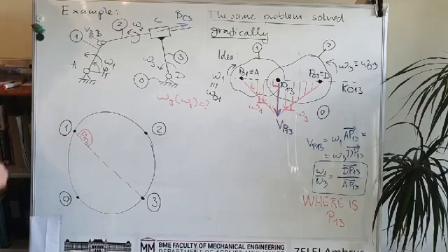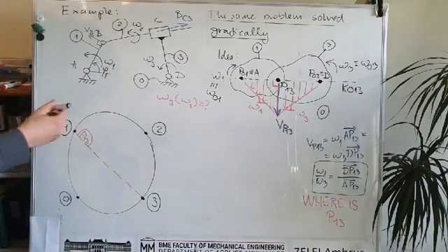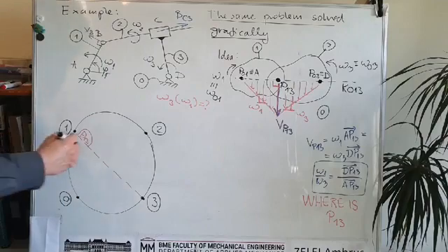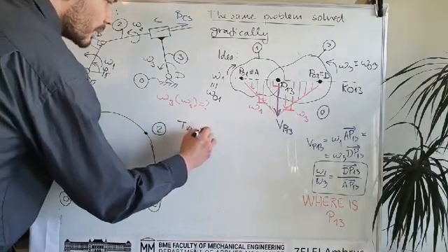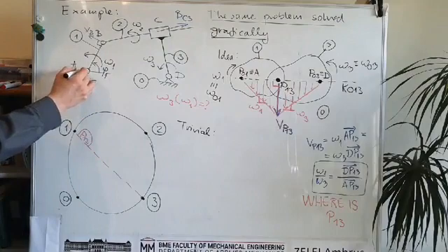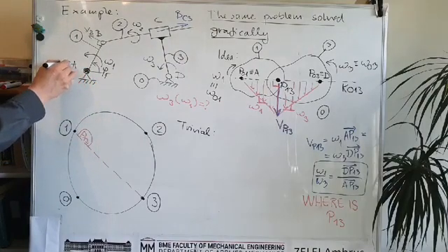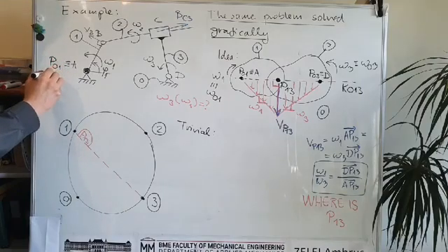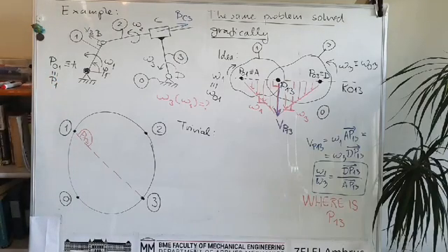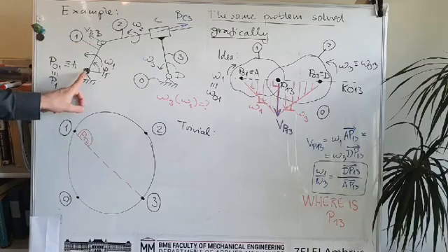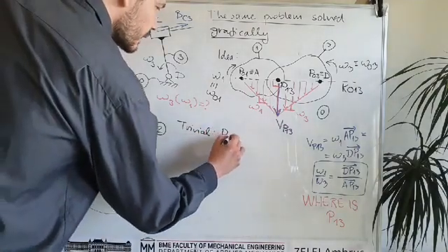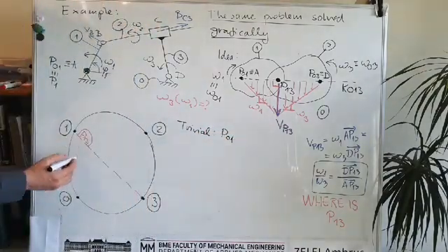So first we should collect again the trivial relative poles. Okay, so the trivial poles are, for example, here, this is, as we said, identical with point A, and basically this is also the absolute instantaneous center of velocity for rigid body number 1, because this is fixed here to the ground and the ground is fixed. Okay, so P01 is trivial, and we can draw it here.